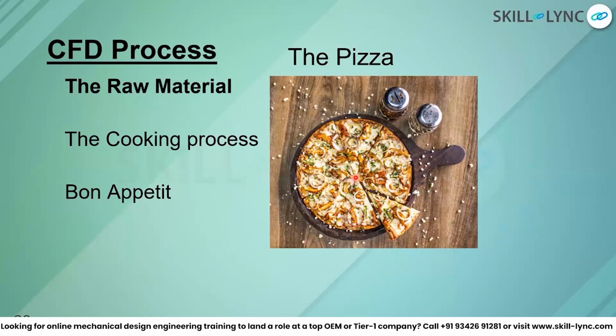As the output, you want to see the drag coefficient of a vehicle. So you will set up a case which will solve all the parameters directly related to the drag coefficient calculation. If you're solving something which is not at all related to the drag coefficient calculation, you will not get the right drag of the vehicle. You will get some results, of course.